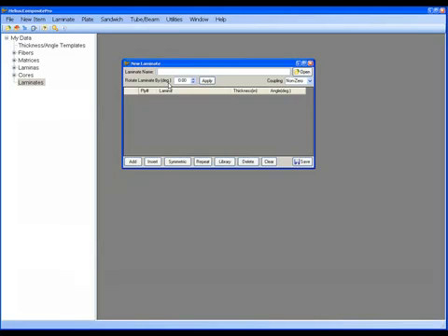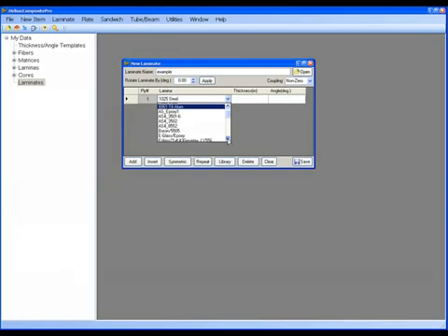So let's start with a laminate here. We're going to call this Example. We'll make, for this example, let's say a 3-ply laminate. Let's use, let's say, the T300 PR319 material. Thickness 5 thousandths.